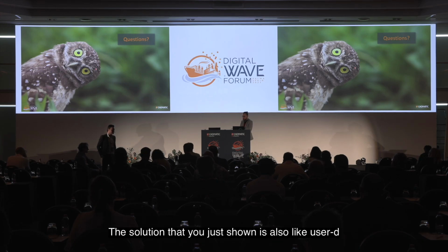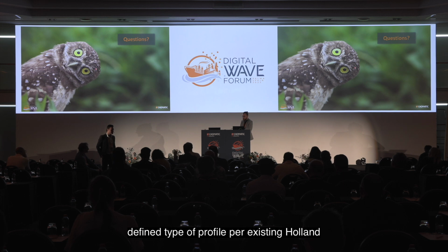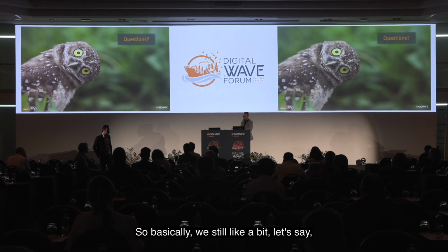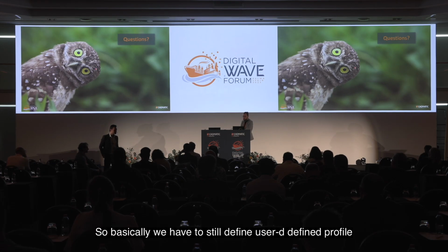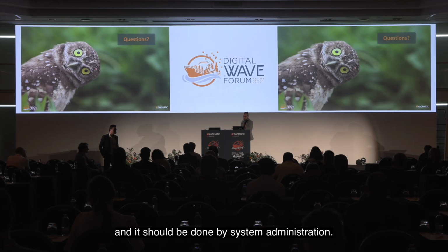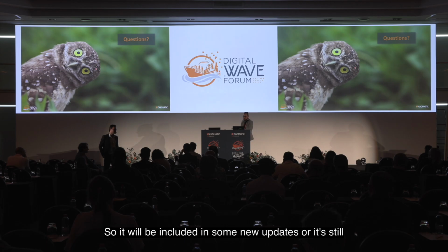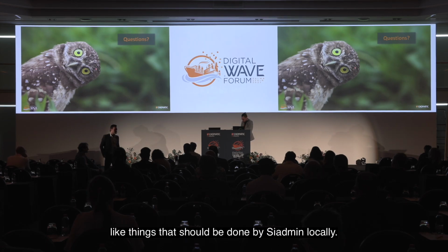The solution that you just showed is also a user-defined type of profile per existing Holland profile built into Cadmatic, right? Yeah. So basically we are still a bit limited, so we have to still define user-defined profiles, and it should be done by the system administrator. So will it be included in some new update, or is it still something that should be done by the sysadmin locally?